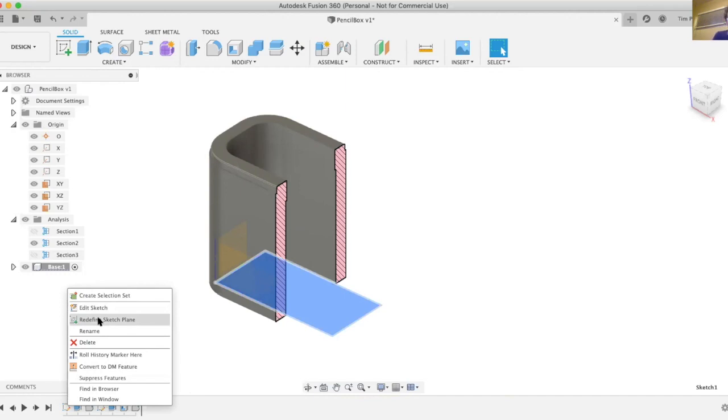But in the context of CAD, parent-child relationships can be kind of important, because when you define a feature on top of existing features, you want to make sure that you're using your design intent in what planes, what surfaces, what faces you're referencing. Because down the road, if you make dramatic changes, that face or plane might not be where you now need it to be.